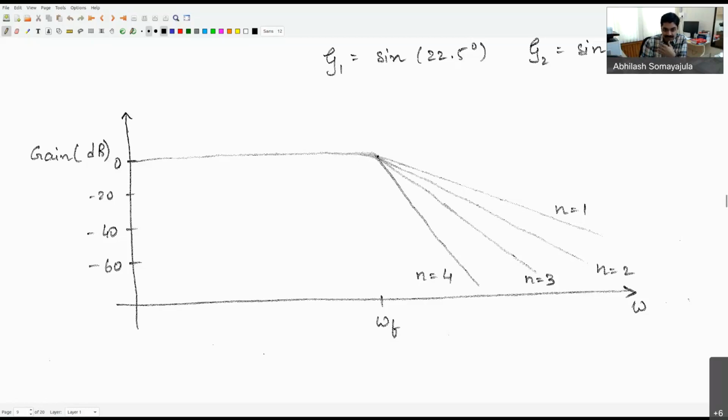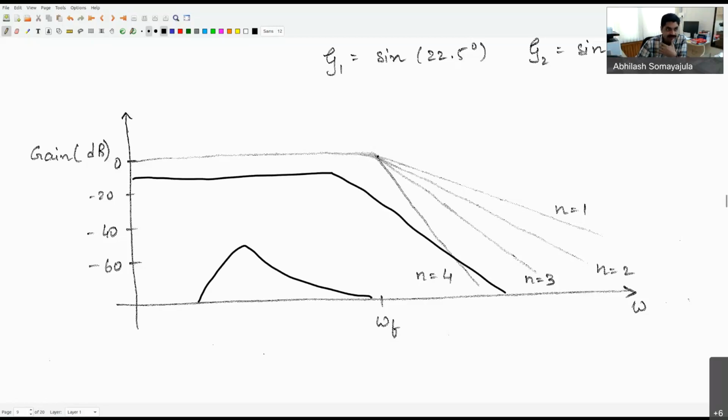So let's say that the control bandwidth was up till here, but the wave frequency spectrum ranges somewhere here. Then what do we do? In that case, you are in trouble because you can't effectively choose a point and say that I'll filter off everything beyond that. Right? So the idea there would be that we'll use something called notch filters. So I'll try to tell you what the main concept is.